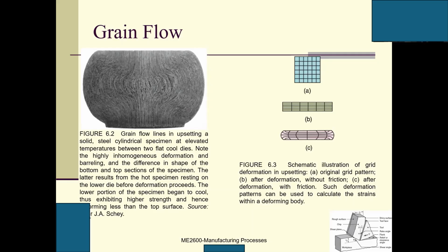This is from this professor. And then we can just use a schematic illustration. So here are the grains. We compress it, and then we have this one. The thickness becomes lower, but it expands this way. But because of friction, we will have this barreling phenomenon here.